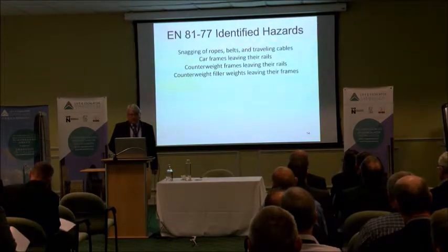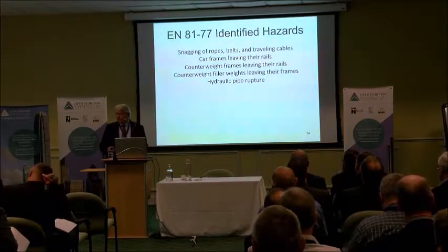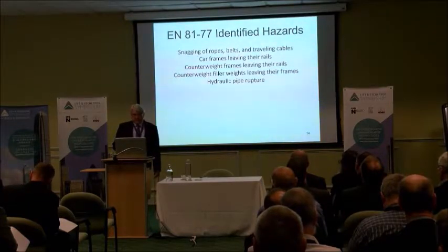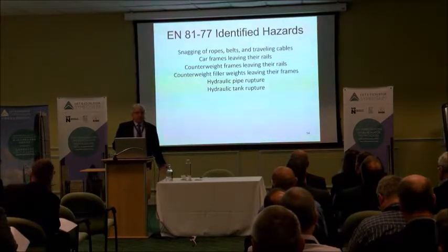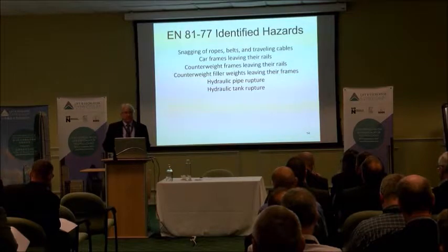The other thing we look for is hydraulic pipe rupture, because if the pipes rupture, you're going to have oil everywhere. It's an environmental issue, but it's more than that, because although hydraulic oil isn't particularly flammable, it can catch fire, and it'll just be another problem. And then you have the general pollution related to the pipe failure. The other part of it is the hydraulic tanks. They're filled with oil, and if they rupture, you're going to have perhaps environmental damage. Now, there's a trend in the industry to switch to vegetable oils, which, if they get away, are non-polluting, but it's still a problem. You just don't want this to happen.